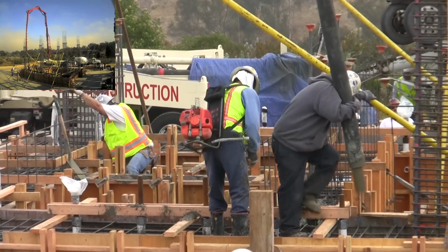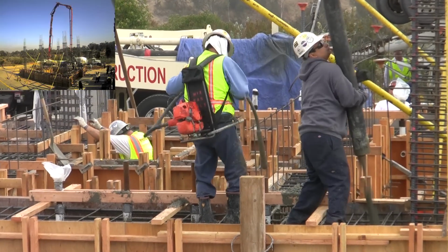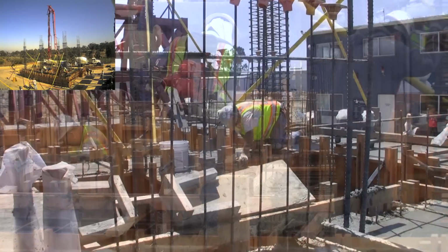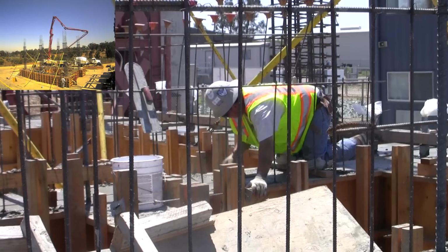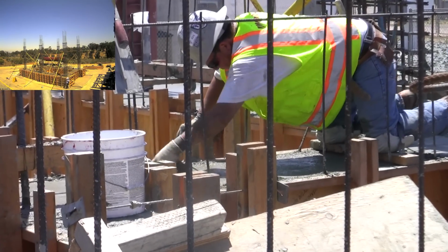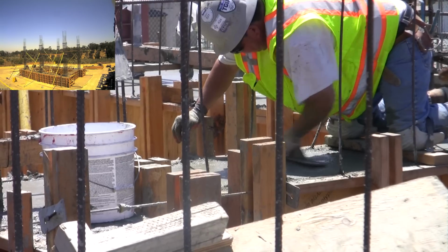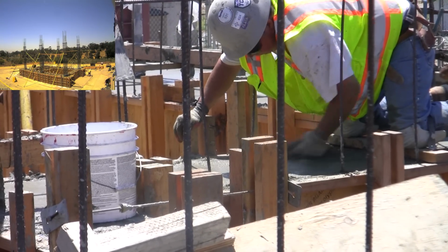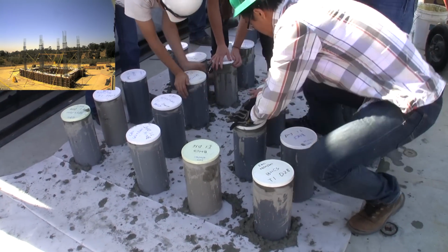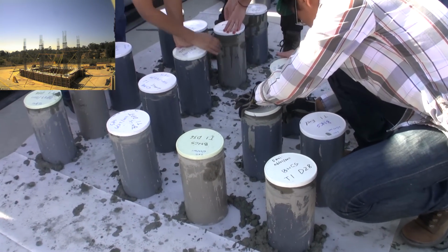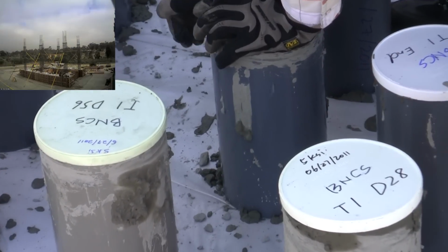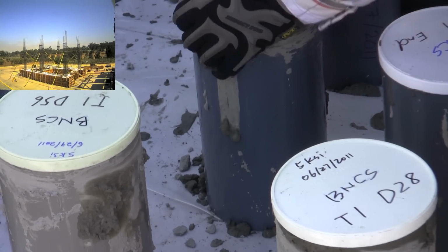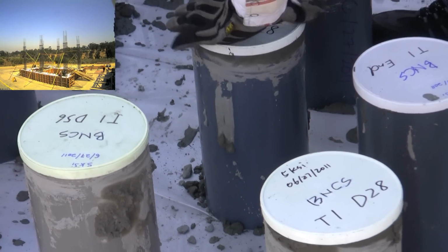Immediately after the wet concrete mix is poured into the formwork, the concrete is vibrated to eliminate voids or air pockets. A large metal or wooden board is then used to screed the top of the concrete. This screeding process helps compact the concrete, ensuring the surface is level and smooth. It also brings near-surface water to the top of the concrete, further aiding in its finish. Finally, the concrete is thoroughly covered with a waterproof layer to control and keep the moisture content preserved during the curing process. During the pouring process, samples of the concrete are poured into small cylinders in order to test the concrete strength during various stages of the curing process. After 28 days of curing, the concrete mix typically attains its design strength, and its rate of strength gain beyond this duration is quite minimal.